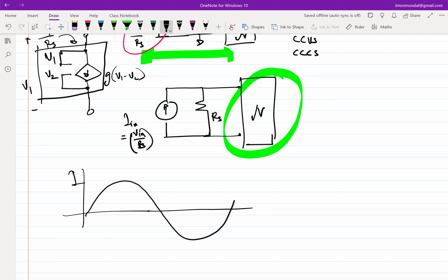Because resistance is essentially resisting the flow of charges, and the existence of resistance comes because of thermal fluctuations inside the material that is making the resistance up. So in other words, with the temperature, the resistance will change, and now temperature is dependent on the current that I am feeding, which means the resistance will change with the current. So resistance is no longer constant with respect to time, and that is a classic case of a nonlinear system,